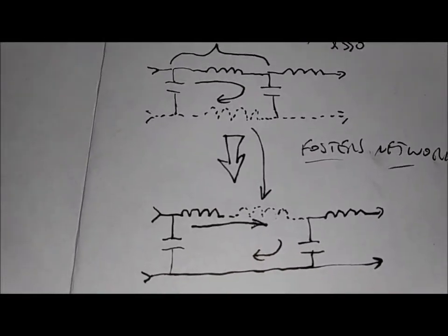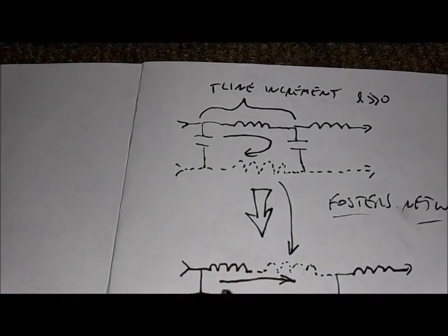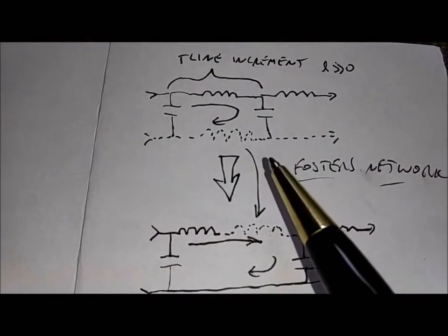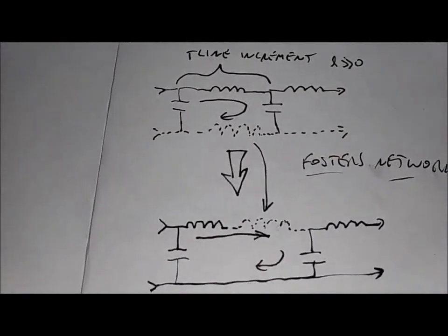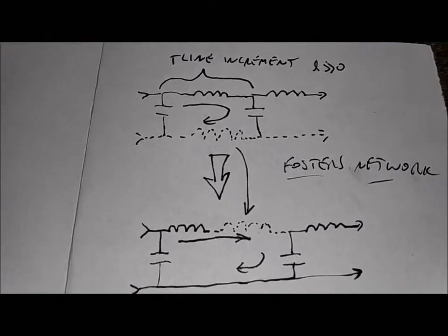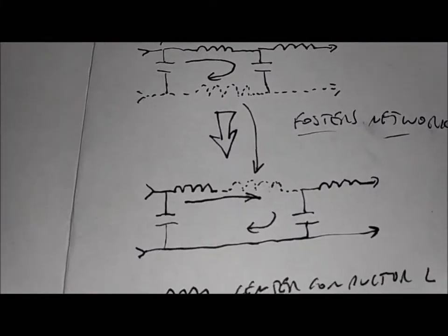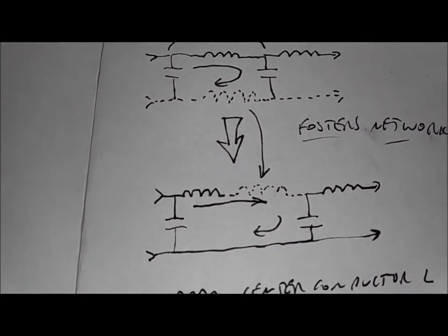Similar principle to the earlier page, but we're still looking at the transmission line in a stepwise model of a long increment. That's not what it really is. That only applies if a transmission line is so short that it's no longer a transmission line. An inch of RG58 at 1 megahertz is not a transmission line. It's a capacitor. 2 feet maybe.